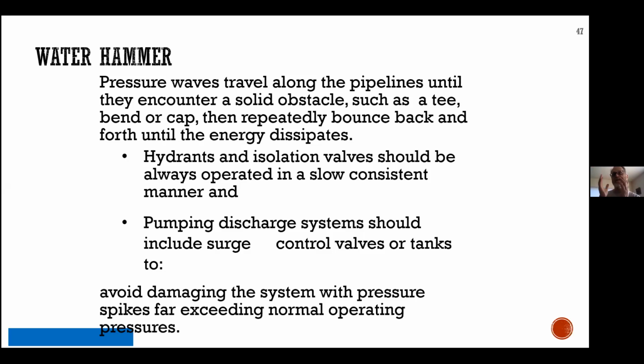It's kind of cool, although it can be very dangerous. So you have to make sure that by slowly closing the valve, it dissipates the energy before it can damage the pipeline or fittings or someone's plumbing and create more problems than the actual initial emergency.